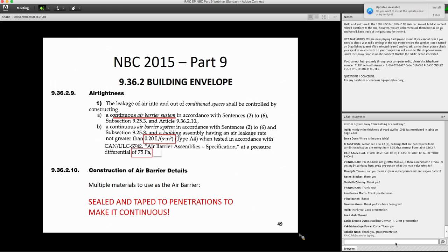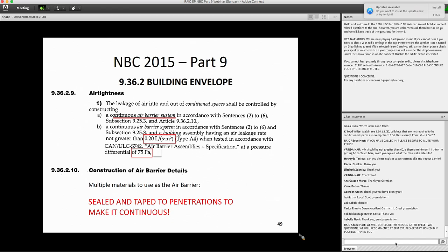Any material means poly, or the plastic that you have, that is 0.005. It can be 1 inch of closed cell spray foam, which is 50, which is below 60. There are multiple membranes that you can buy, Blueskin, Intello, Cosella-Dörken, that are low vapor permeance. And in the spec, you have to check that that membrane is below 60.